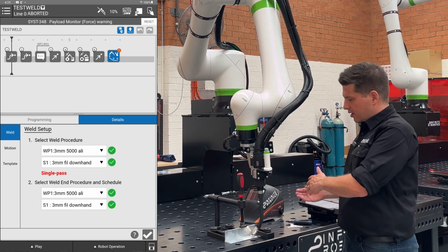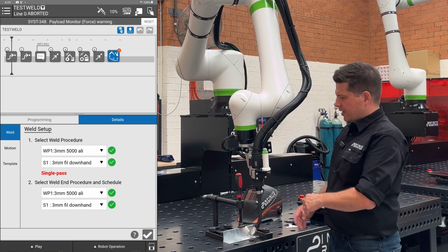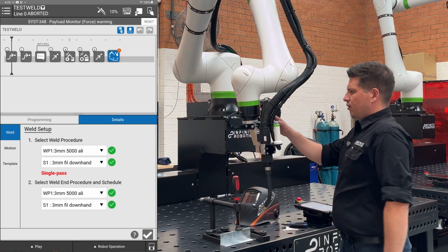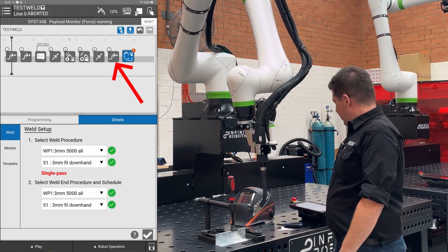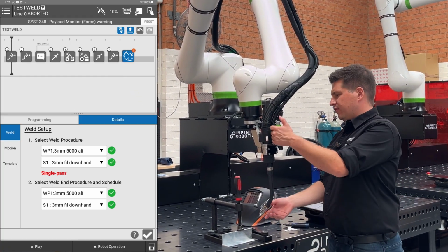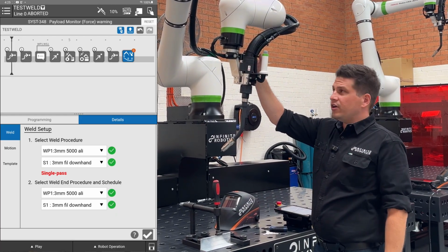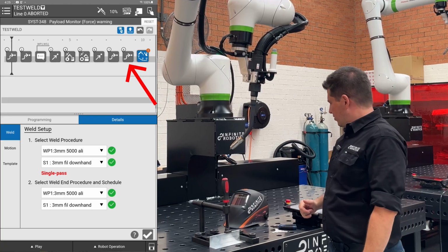So from the welding end, just like the welding start, we need to make sure that when we go to our next point, we're not going to run through the jigs or the parts, so you need to come out to a safe position about here, press and hold the button, and that inserts another air point for us. And then we can move the robot back up here, ready to go to its next weld. Press the button to record the position.